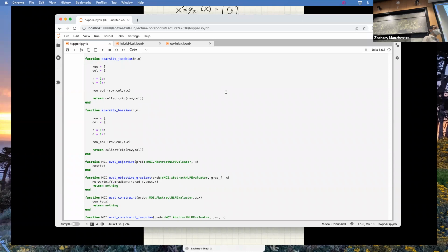There's typically no vision in these control loops. Sometimes there are foot pressure sensors in various ways. Usually it's just proprioception, measuring joint angles and motor torques and stuff like this to figure out if you're in contact or not. It's surprising, but those QP based MPC controllers, I said a lot about this earlier, work incredibly well and are really robust. Basically all the walking robot stuff you see today is doing some form of QP based MPC with linearized dynamics. It's surprisingly robust. So that's pretty much what they're all doing.